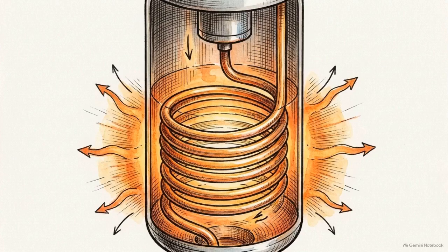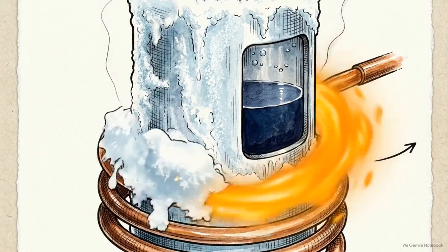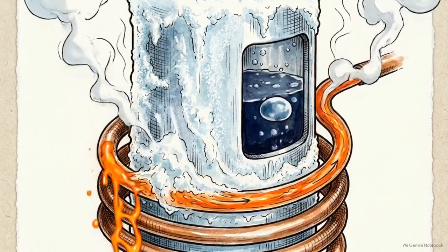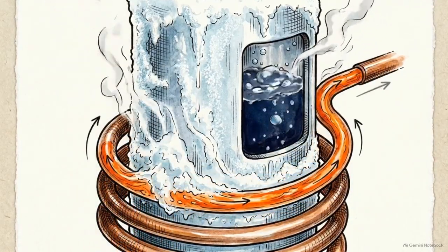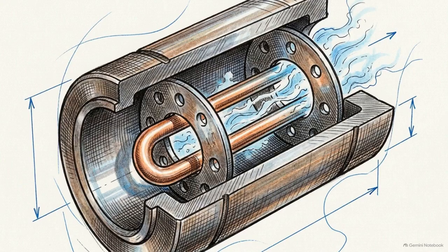Some systems employ a heat exchanger accumulator combination for enhanced performance. This design uses heat from the high-pressure liquid line to actively boil off the trapped refrigerant inside the accumulator shell. Regardless of these external variations, the internal dimensions and orifice sizes are precisely set by the manufacturer to match the compressor's requirements. The spatial footprint may change, but the core objective of fluid deceleration and metered return remains the same.